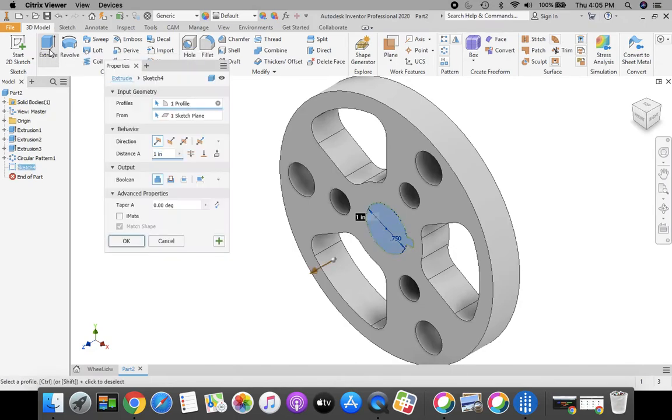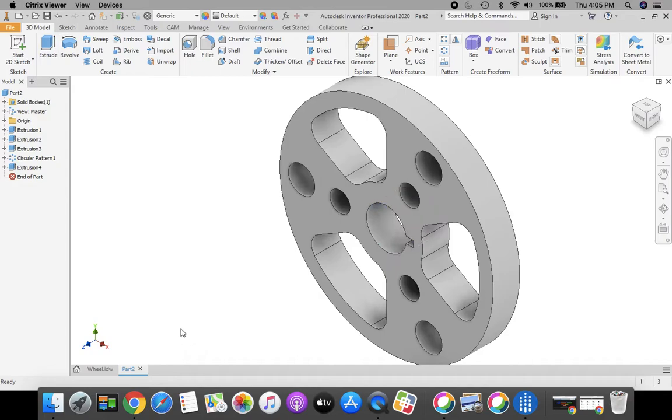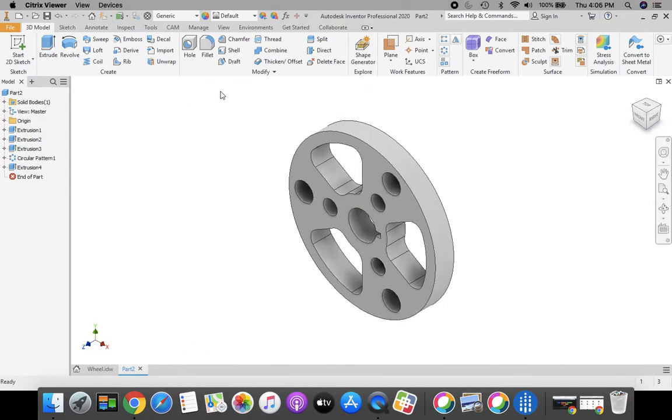So let's click extrude. We're going to extrude, cut all the way through all right here, click. That should inactivate your cut command, and click OK. Great job. The next thing that we need to do, go home. I'm going to come up to the top, go to default.